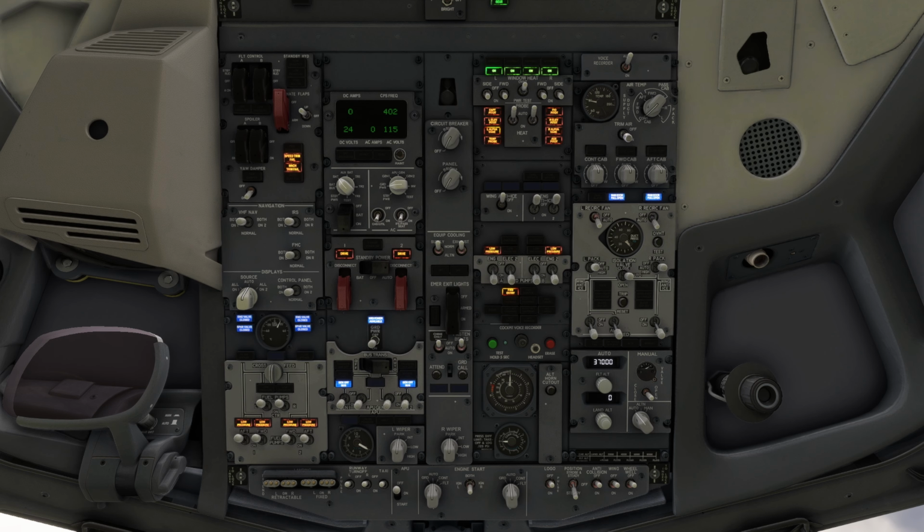We're going to close Navigraph charts and we're just going to dial this in. We're going to round it to the nearest 50. So since 13 is already closer to 0, we're just going to leave the land altitude to 0. Very straightforward. Now, what we want to do here is select either ignition left or ignition right. Whichever one you want is fine on the engine starters. So I'm just going to go with ignition right.